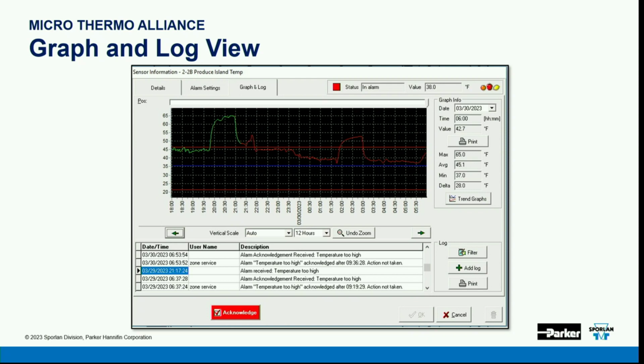If it's a high priority alarm, the bells and whistles in the store might go off. We'll send a text message or an email out. And to acknowledge it, you simply click on the acknowledge button in that active window. Your name will be there because you're already logged into the system. You put your password in and then put one or two sentences. You don't have to write War and Peace. Just for the next guy that's coming along, put the action that you took to solve the alarm. Click acknowledge, and then the alarm goes away, okay? And that history is retained in there for up to a full 5.5 years until it becomes so old it drops off at the end and we put new history on, okay?